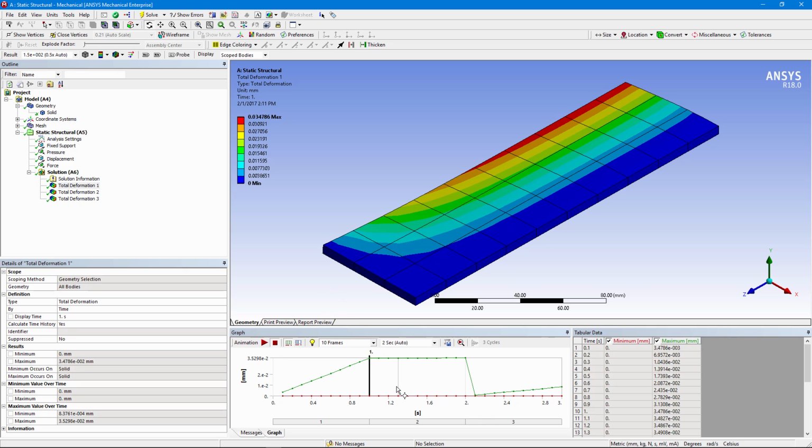In the second load step, we're not seeing any big change in the amount of deflection, but there is something happening. What's happening on this edge? The constraint on vertical movement is being backed off gradually through these substeps. Let me run it as an animation. I'm going to animate through the results, not by linear interpolation. And let me run that animation over 10 seconds.